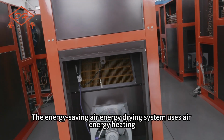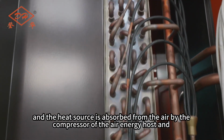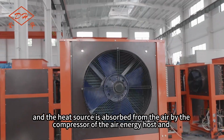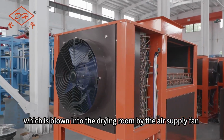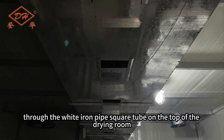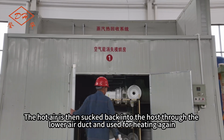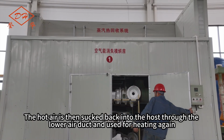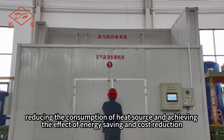The energy-saving air energy drying system uses air energy heating, and the heat source is absorbed from the air by the compressor of the air energy host and converted into hot air, which is blown into the drying room by the air supply fan through the white iron pipe square tube on the top of the drying room. The hot air is then sucked back into the host through the lower air duct and used for heating again, reducing the consumption of heat source and achieving the effect of energy saving and cost reduction.